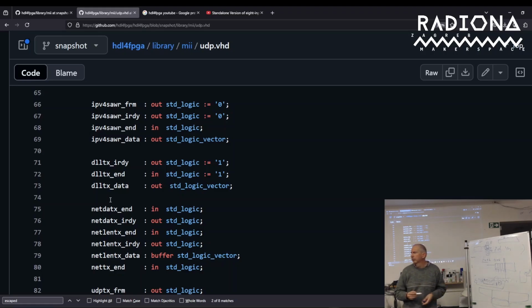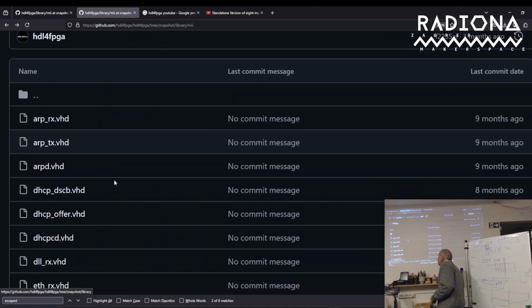What is happening, for example, if you receive a packet with wrong CRC? Because if there is a logic that you process everything as it comes, then in the end there has to be some kind of rollback or discard logic. Yes. Whatever you calculated so far is not valid because the CRC is not valid.